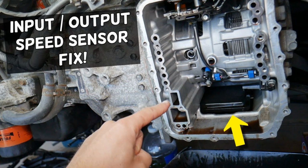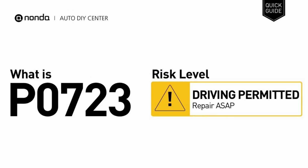Measure the resistance by removing the connector and using a digital multimeter adapted to the ohm scale. If the resistance is out of range or above the limit, replace the sensor. Check that the sensor and the PCM wiring harness connector are energized using the factory wiring diagram. If the OSS sensor is on the same line as the TFT sensor, the voltage will vary depending on the temperature of the transmission fluid.